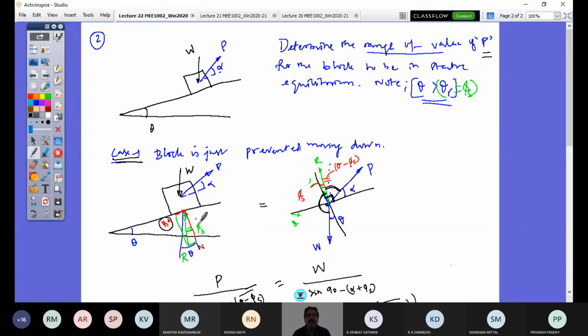So you see that your reaction to the vertical is now theta plus phi instead of theta minus phi, and the expression would change accordingly. So draw the free body diagram and try to get the upper value of this range in a similar approach, and then you have the answers for 3 categories depending upon the direction of application of force P.